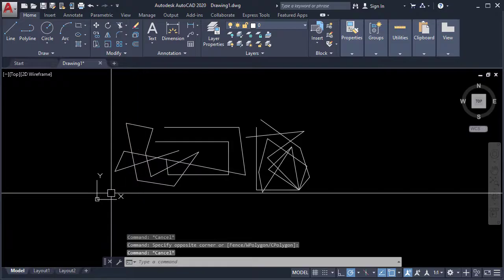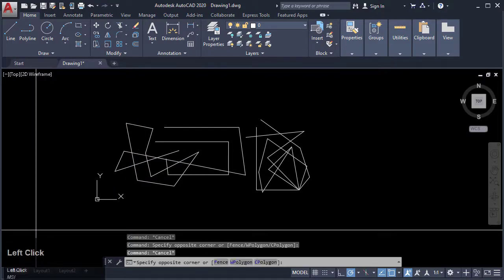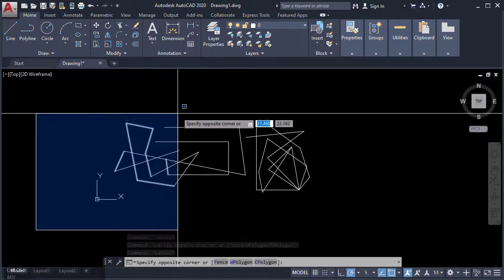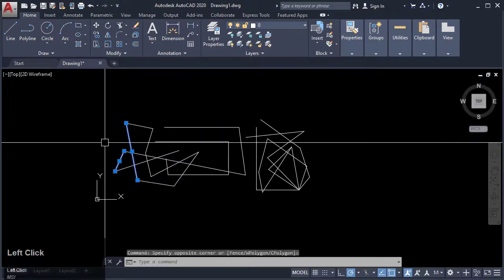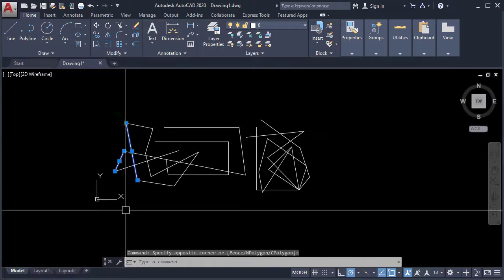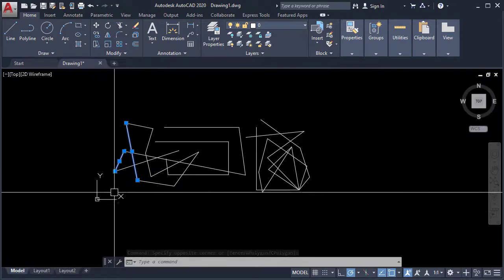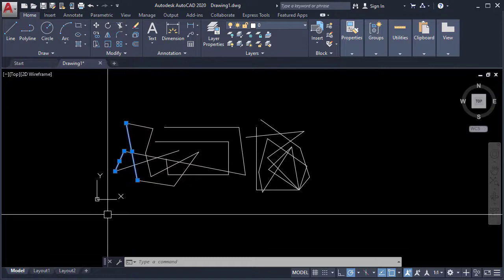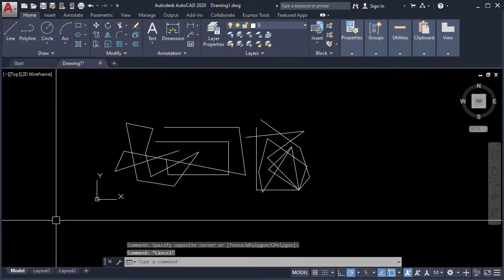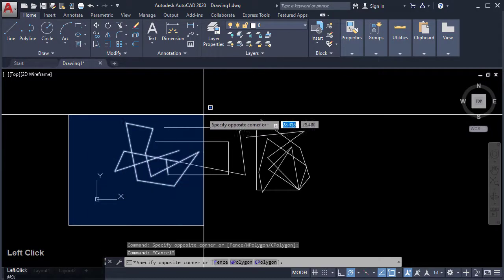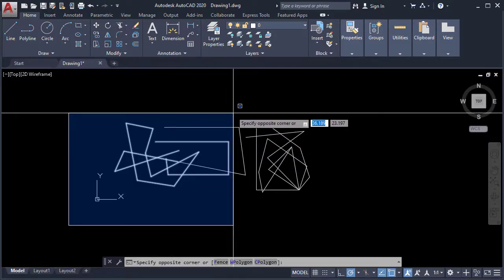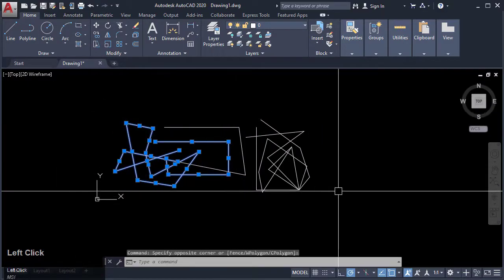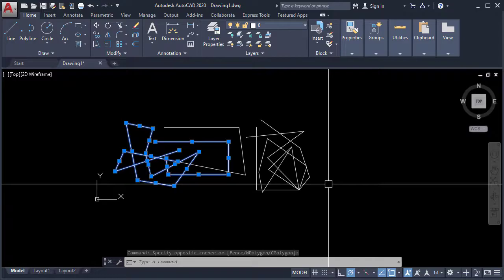However, if you are going from the other direction, click, release, then partial selection. Let's try that. One thing that you will notice, it will select only entities that are entirely inside the blue rectangle. Let's do that again. Click, release, and drag. It will select only items that are completely inside the blue rectangle. So those are the two ways of selecting items in AutoCAD.